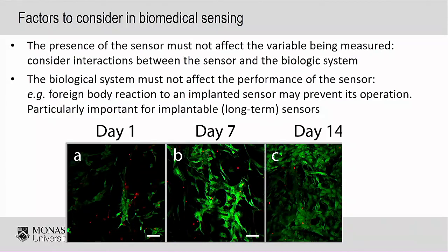Because a lot of sensors rely on having basically a free barrier between the sensor and what they're measuring. For instance, if you think of blood pressure sensors, they typically work on strain, and they might have a small barrier in there that essentially moves, and that's how they detect strain. If that barrier were to have tissue growing into it, it wouldn't deform the same, so it wouldn't measure the pressure very well at all, or it might even become completely occluded. So these are very important things to think about when designing a sensor.